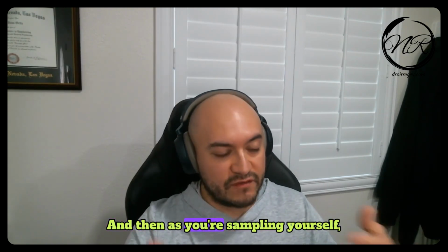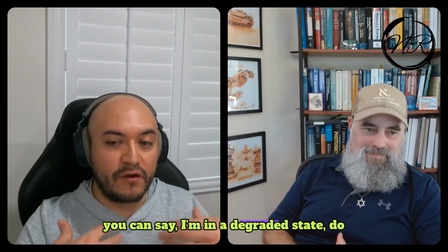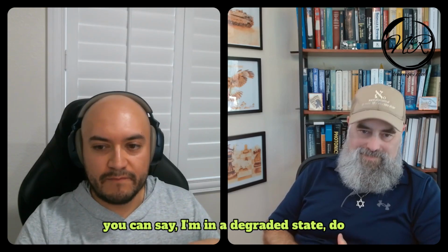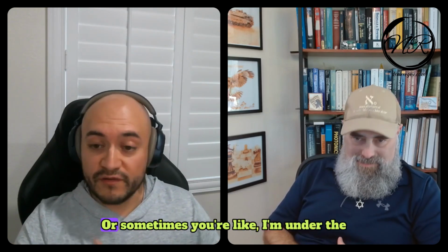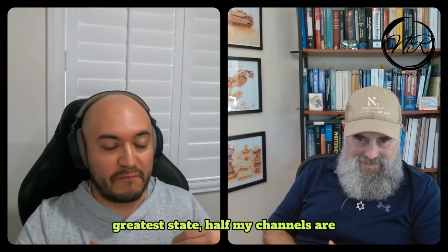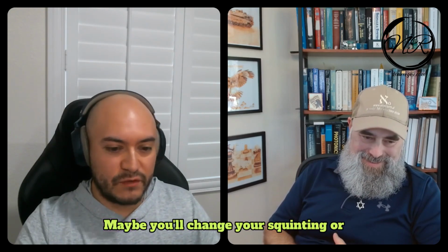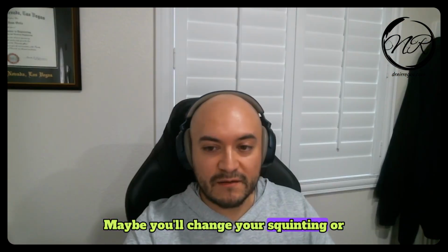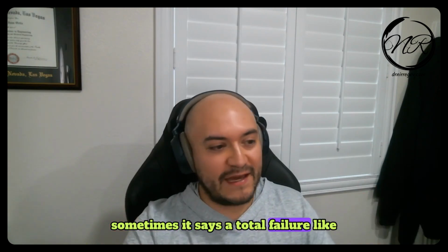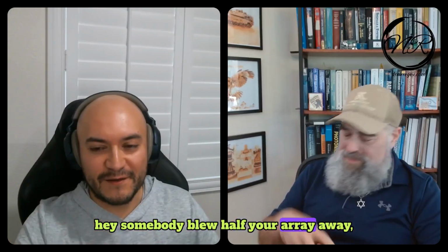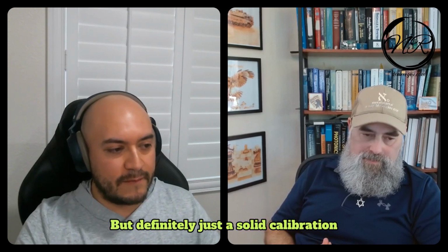As you're sampling yourself, you can say, I'm in a degraded state, so do an on-demand calibration. Or sometimes you're in a degraded state where half your channels are gone, so you do something else, maybe change your squinting. Or sometimes it's a total failure, like somebody blew half your array away, and you're done. But definitely you need a solid calibration routine.